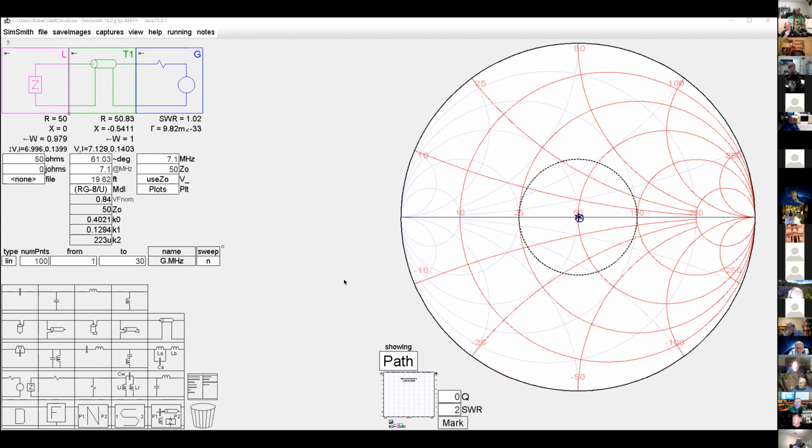Yeah, Roby, if I may add on to that comment, the article requires you to take a vector network analyzer and pull some data off of the point where you want to match it. It uses that information, and in the analyzer I have, which is an AA54, you have to pull it off and turn it into what's called a touchstone file, which is a comma separated value file with the reactive elements in it. Then SimSmith uses that to design the network for you as you interact with these modules that Doug was pointing us to down in the corner there.